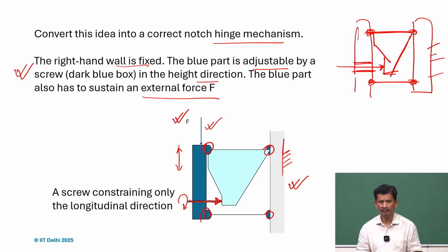But if we remove it and we only look at this part, this looks like just the mechanism we discussed earlier, and one can easily make the mistake of putting all the hinges there with the same orientation. So one can find that, oh, it's a symmetric design, and we can go about that. But if we look at it closely, what we realize is that the force directions might be different.